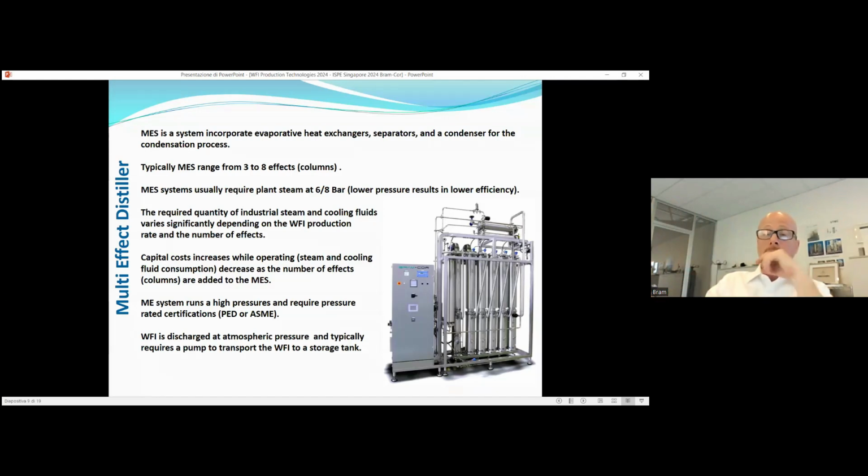Another thing to be noted is that, being a pressurized machine, it is subject to codes, for example the PED in Europe and the ASME stamp in the US, which have an economic impact on the machines. The WFI is discharged atmospherically, so it typically requires a pump to transport the WFI to the storage tank, or the storage tank has to be at a lower level than the WFI outlet of the distiller itself.